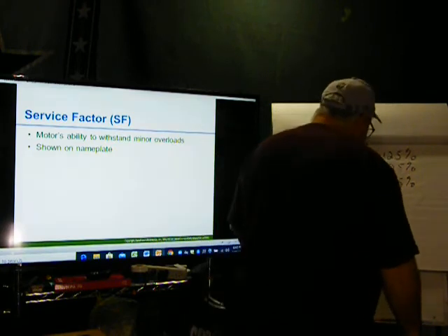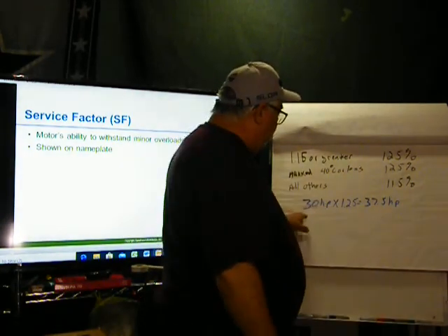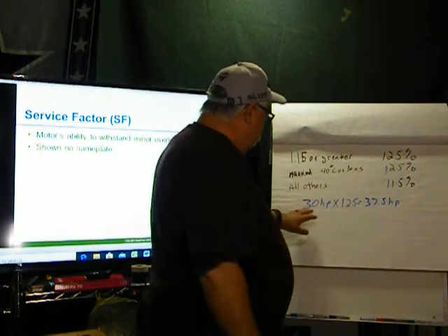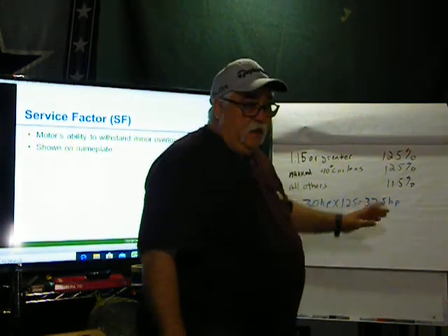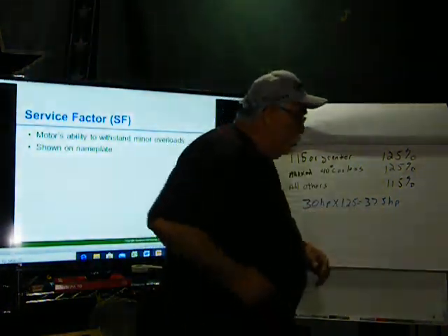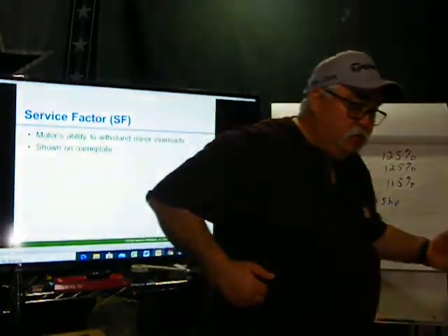So if you multiply the service factor times the motor horsepower, that's what it's allowed to go up to, according to what the book says.